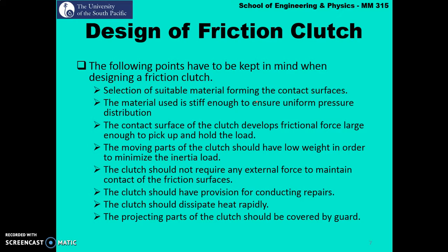The clutch should have provision for conducting repairs, just in case you need to do some maintenance. The clutch should dissipate heat rapidly, because we understand that if heat is not removed, the material from which the clutch is made is going to lose its mechanical properties. And then finally, the projecting parts of the clutch should be covered by a guard. So this is very important.